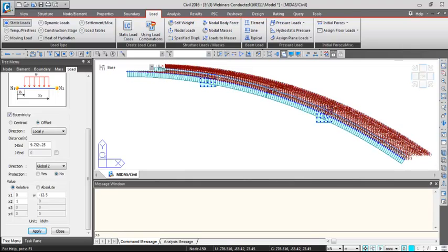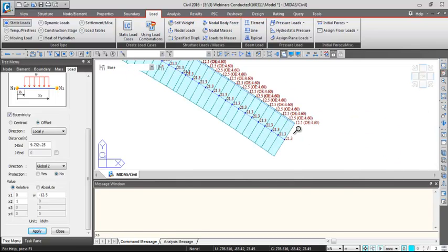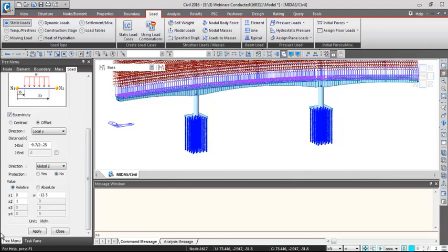Okay, so I'll just zoom in. As you can notice, the software auto calculates even from these kinds of input, and you don't need to calculate the value manually elsewhere and put it on. You just enter the formula and it will calculate. So this has been done once. Similarly for the crash barrier on the other side, I'll click on select previous, change this sign to minus, and say apply. So the crash barrier load has been applied at both the locations.